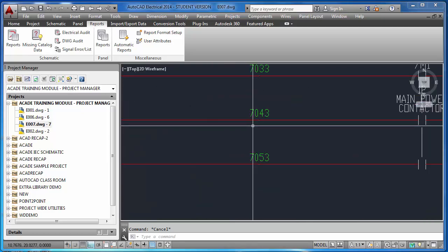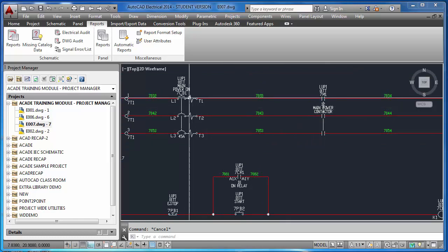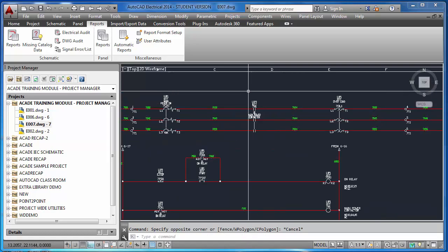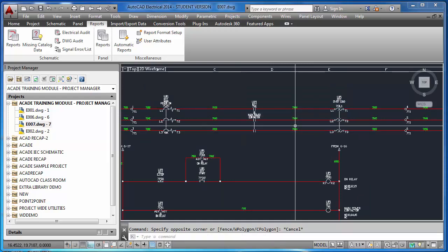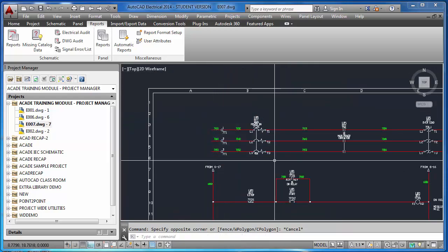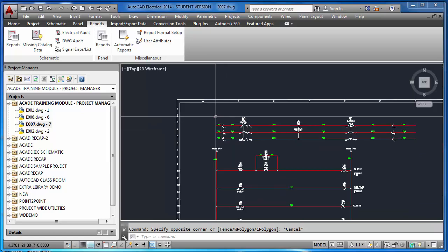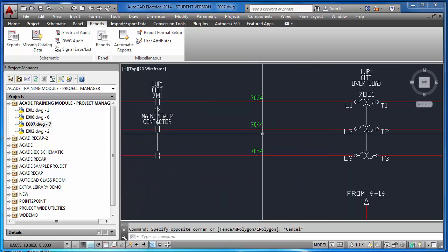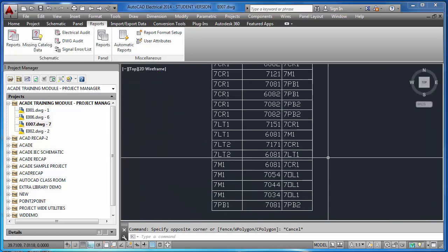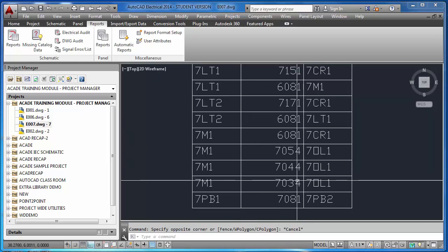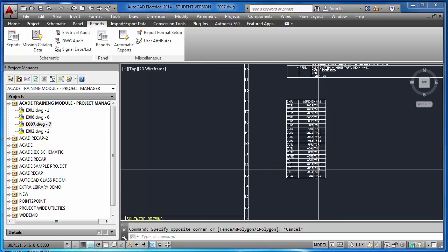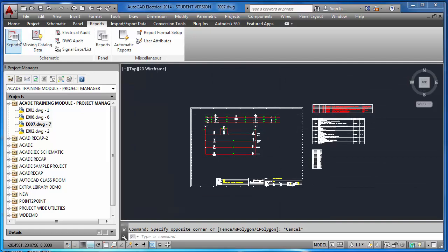You can see it here, 334353, in between these two, from this CB1 to this. And similarly you can see these two as well, but here you won't get it because it is not coming from a component. Unfortunately these TBs are not considered as components, okay. Now you see here 344454, the last two digits, 344454, here it is. So from to is basically from which component, to which component, and what is the wire number in between these two. You will get that detail from from to.